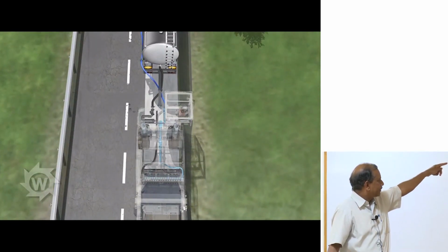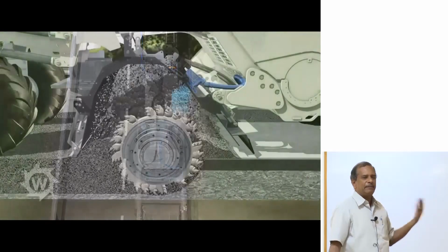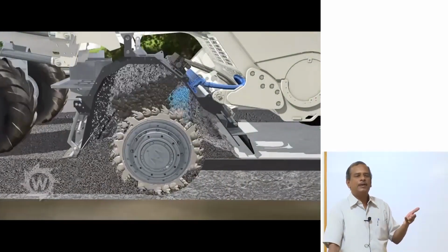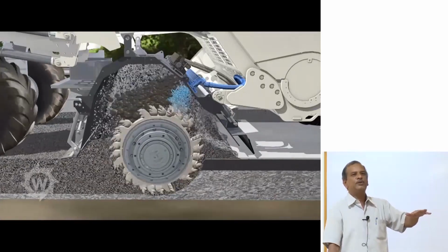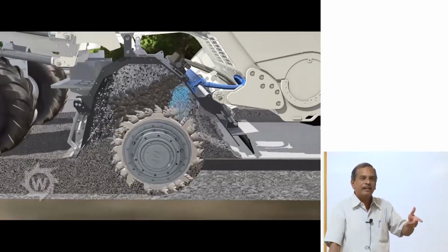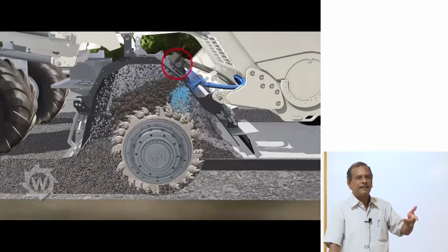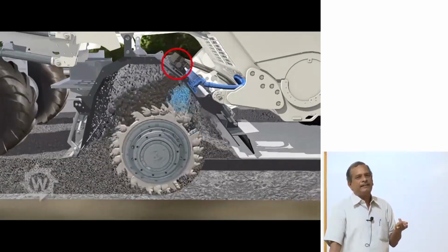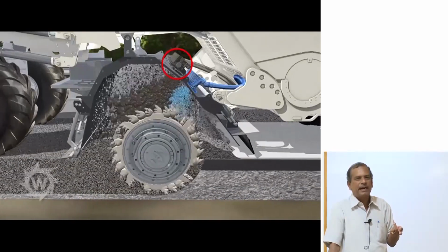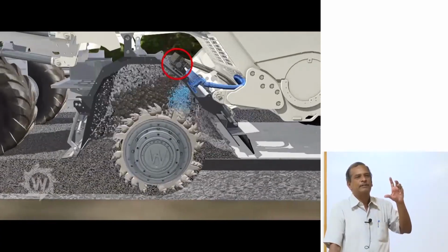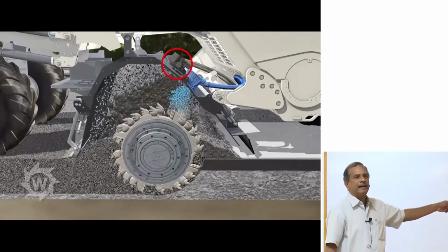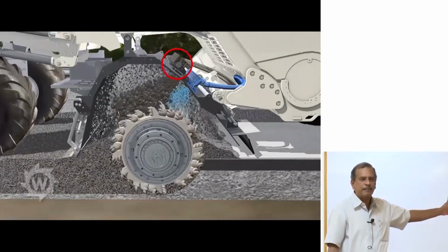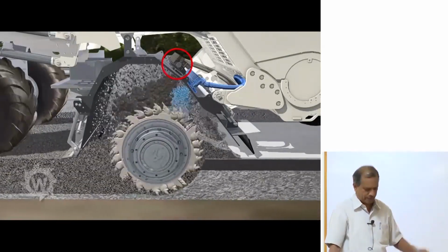I have a tanker of water. I try to mill the material. To the milled material, I add the foam bitumen, lay it and compact. So this will result in reuse of the material and stiffening of the aged materials. I try to rejuvenate the oxidized aged bitumen, and by this process, I can reduce the thickness of the bituminous layers. So this is one way of reusing the material, and this technology we have started adopting in several highway projects in the country today.